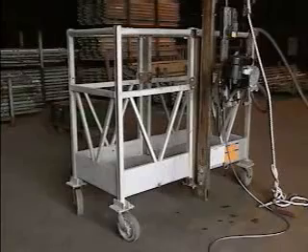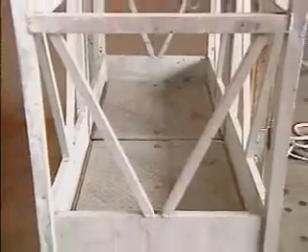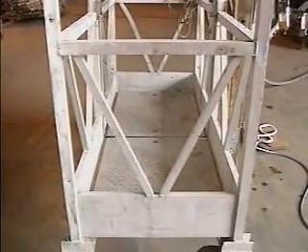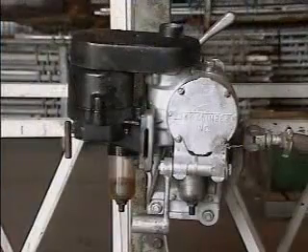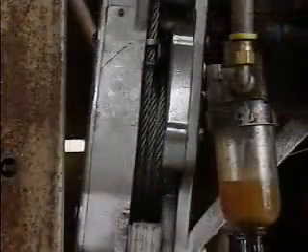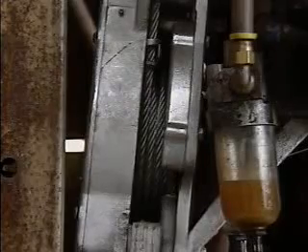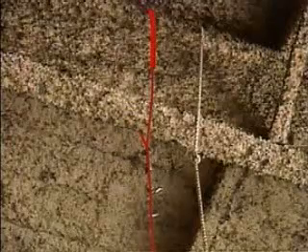Here's the pneumatic scaffold that we'll use for our discussion. It has a work platform, or floor, for the worker to stand on, and a protective cage to prevent the worker from falling off. A pneumatic hoist mechanism is used to move the scaffold up and down a cable. One end of the cable is reeved around a drum inside the hoist mechanism, and the other end is attached to a beam or a similar support overhead.